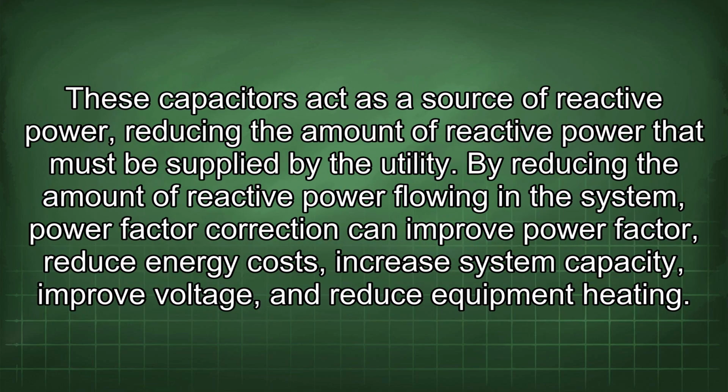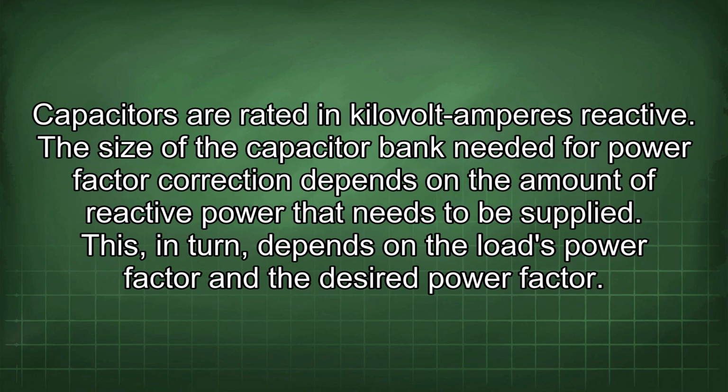These capacitors act as a source of reactive power, reducing the amount of reactive power that must be supplied by the utility. By reducing the amount of reactive power flowing in the system, power factor correction can improve power factor, reduce energy costs, increase system capacity, improve voltage, and reduce equipment heating. Capacitors are rated in kilovolt-amperes reactive.